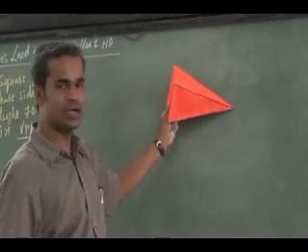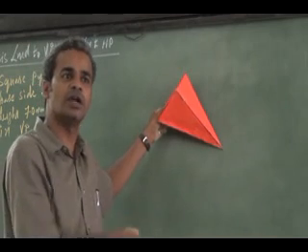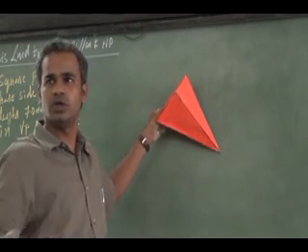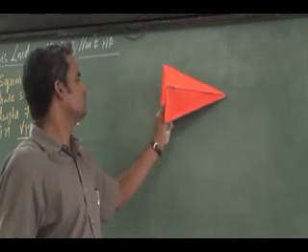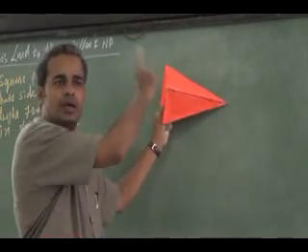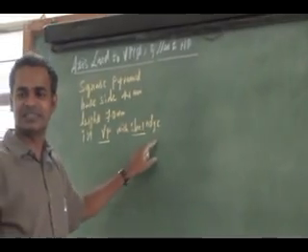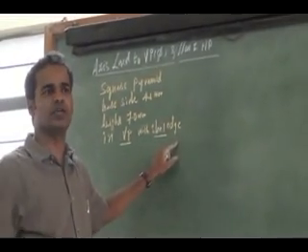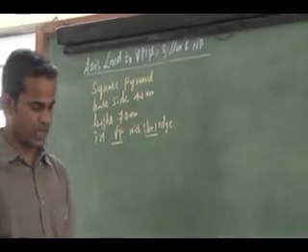If this is the orientation, the axis is inclined to both planes, and I told you that in your syllabus you don't have both inclinations. So the axis is inclined only to VP and it is parallel to HP. So it is in VP with a slant edge such that the axis of the pyramid is parallel to HP.